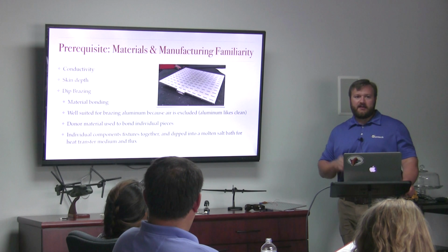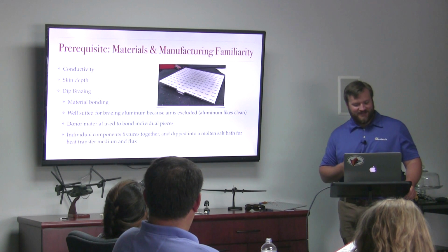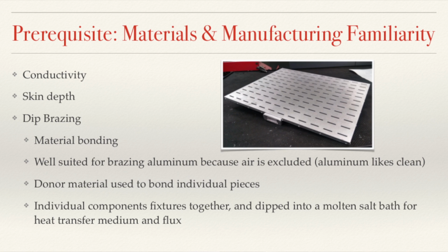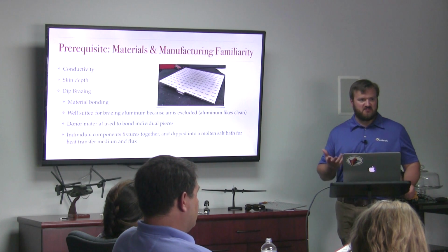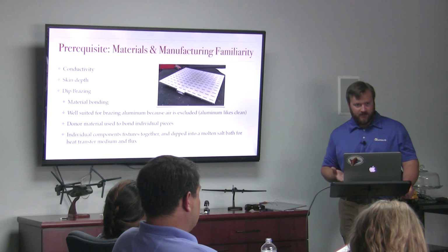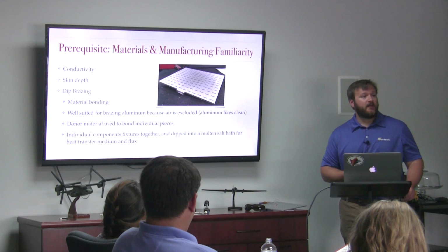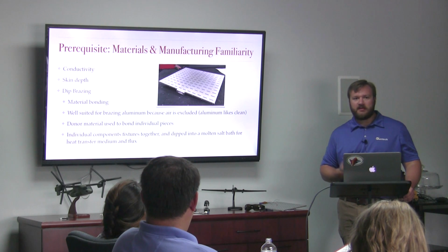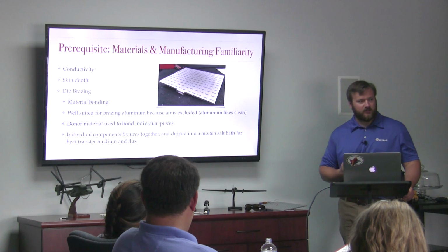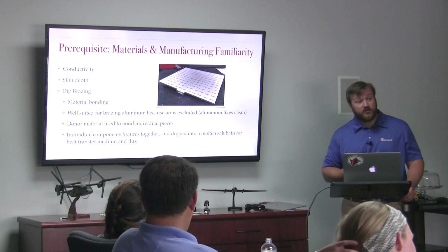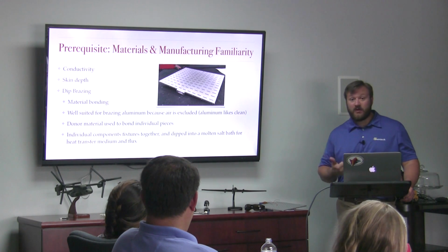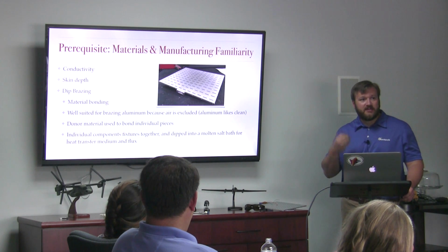Now this is the part that Rich and Sarah have had so much fun with, is how do we build this darn thing? The material we're using is going to be 6061 aluminum. I don't know, what does it come out? Not too soft, not too hard. It's like a T651. It's T6. Oh, it is T6, not 651. Okay. So it's a good general purpose aluminum. It's not one of these crazy unweldable, unbrazable type materials. It's something that shares a common characteristic, though, with all aluminums, in that if you're going to weld it or braze it or do anything, it likes to be extremely clean.